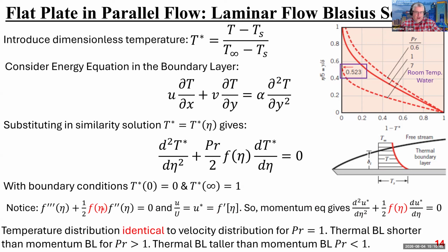So it appears here in red and it appears here in red, just to remind you that the reason this doesn't get bumped up is because we already know the solution, right? And so the same is true here, right? The reason that this doesn't somehow change is because this is that same function of eta from the velocity, from the Blasius solution. Okay, so how cool is this, right? We basically now got a way to solve the temperature field inside the thermal boundary layer from the velocity field inside the momentum boundary layer, right? This couldn't be like more amazing and ideal.